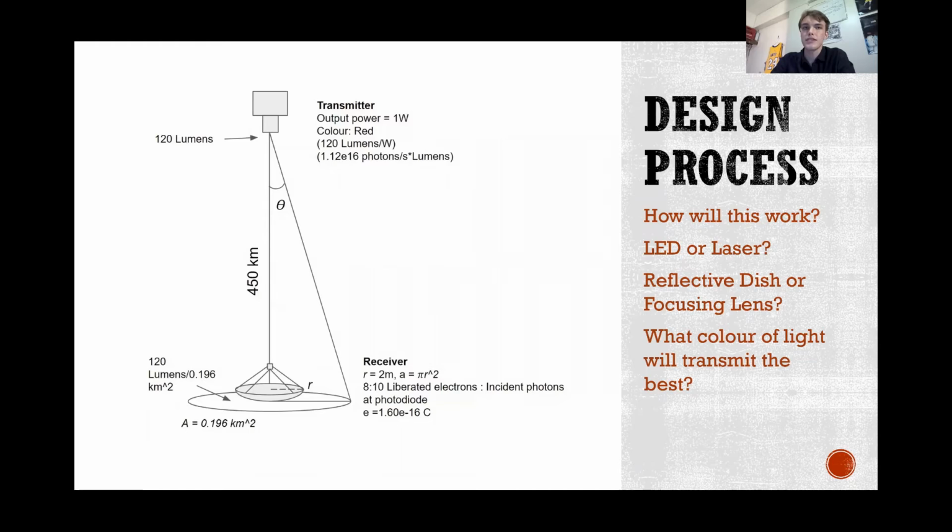To do this effectively, the transmitted light, or absence of it, must create as large of a change in luminous flux at the surface of a photodiode on the ground as possible. For this will induce the greatest electric current into our receiving circuit. This means that the light coming from the transmitter must be as concentrated as possible, and the receiving module must be able to focus a large amount of light into the diode for the best results. And to send the most concentrated beam of photons, the team chose a laser over any LED configuration, as lasers had a much lower diffraction angle, keeping the beam more concentrated over the distance.